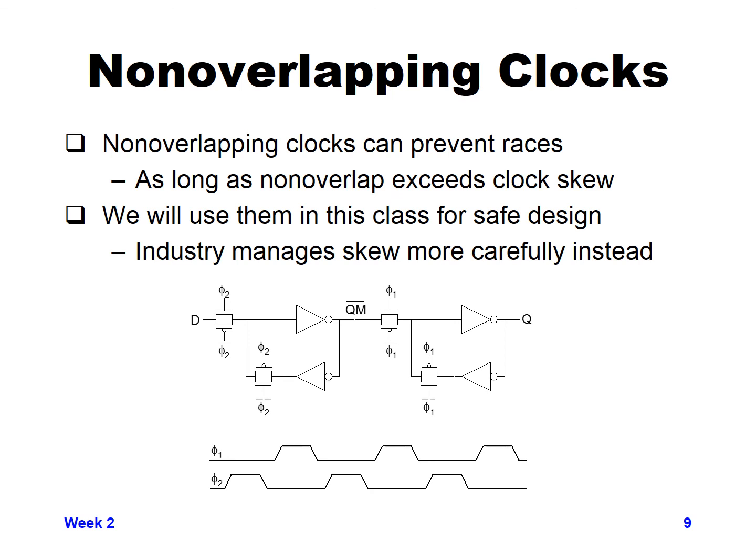So the time that each clock is high is not switching at the exact same time, as you basically get a phase 1 clock and a phase 2 clock, and those go high for less than 50% of your cycle, and you make sure that there's space between the transition of phase 1 going high and phase 2 going high.